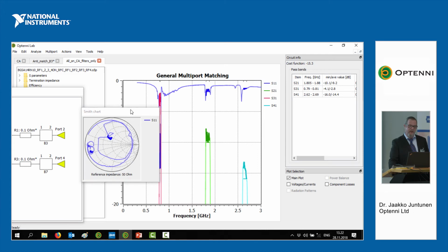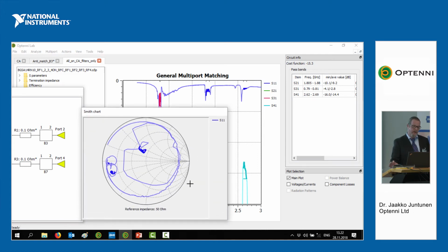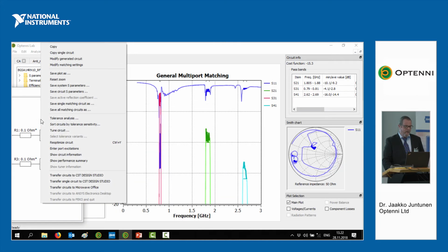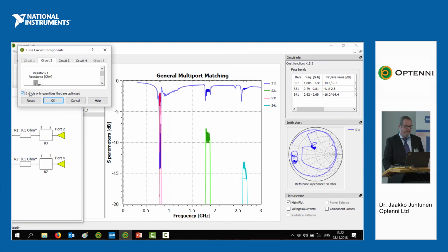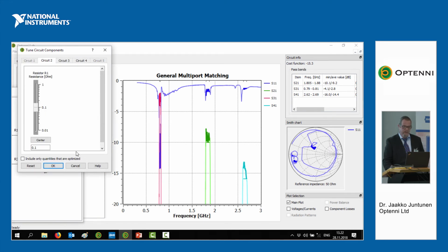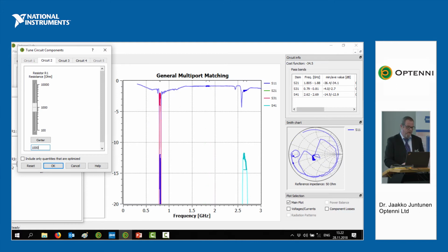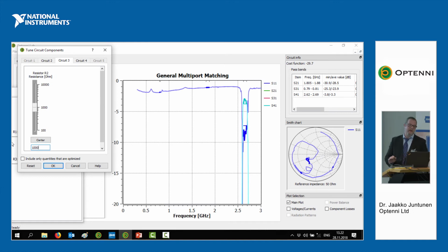If we look at the Smith chart plot, the darker color shows the different frequency bands. Band 20 is quite well matched, while band 7 and band 3 appear close to the short circuit. And if I tune, for example, one of the resistors, so I more or less cut the branch for band 3, this is for band 20, and now we have only band 7 there.